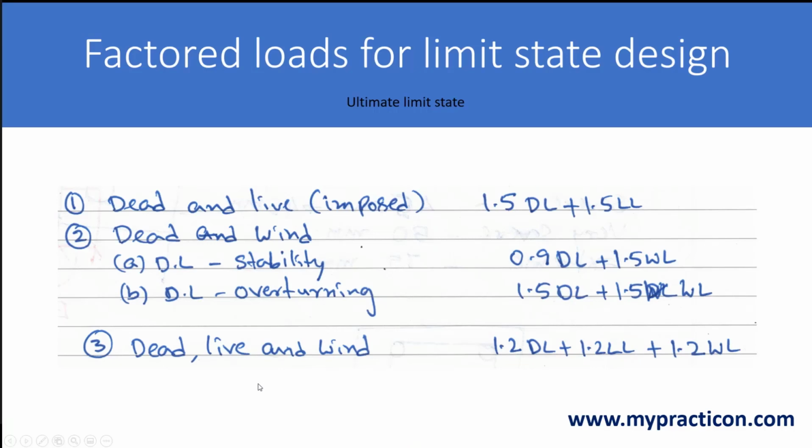Now we have learned the stress strain curves, and we go to the factored loads generally used in reinforced concrete design. The load factors are recommended for safe and economic design. Whatever the loads are, we further factor them, like 1.5 times DL, dead load, plus 1.5 times live load. This is one of the combinations.